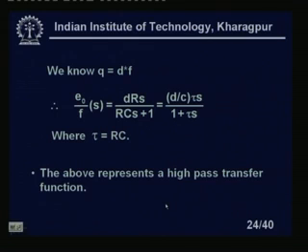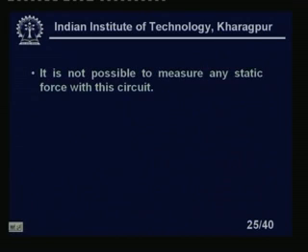The above represents a high pass transfer function. So, it looks like it is not possible to measure any static force with these circuits. Please note, static is not possible, so only in the dynamic case, whenever there is a change in the force, can I measure and get an output, otherwise we will not get any output.